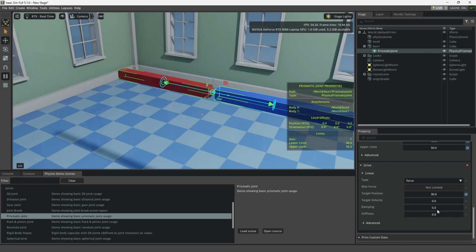Interesting. Do we need to bump up the stiffness? That did something. So there's something between the stiffness and the dampening that I really need to wrap my head around, because between these two, would we have gained anything by just adding dampening? Let's try this again. Run the simulation, no stiffness. Double click the dampening and add 100.